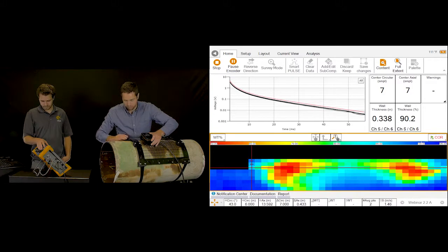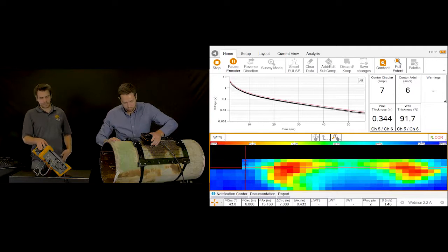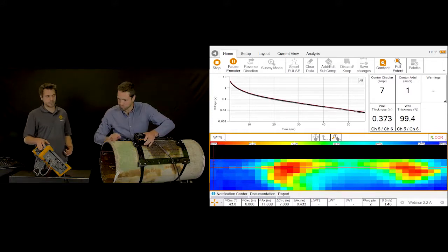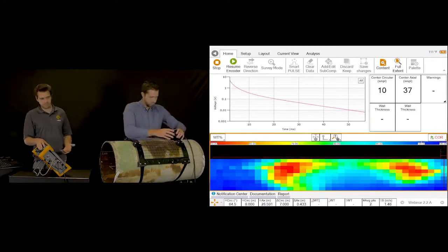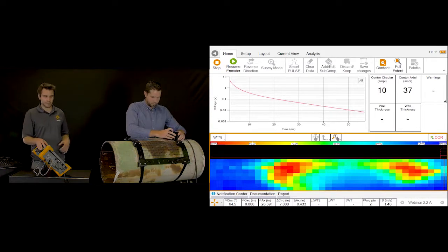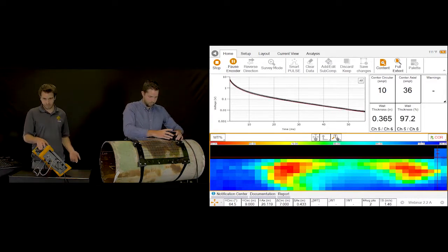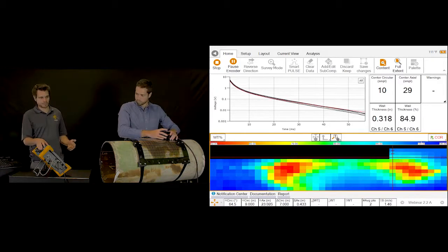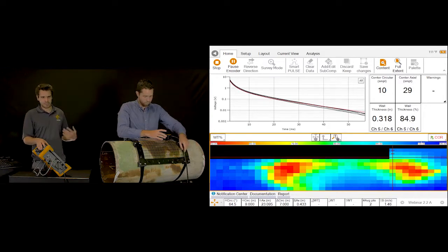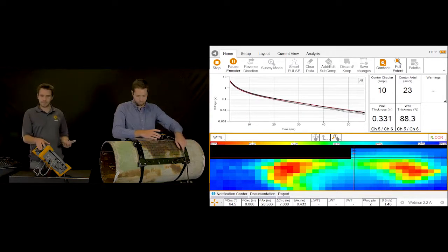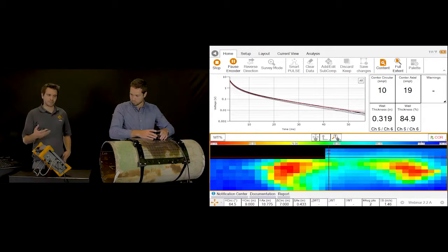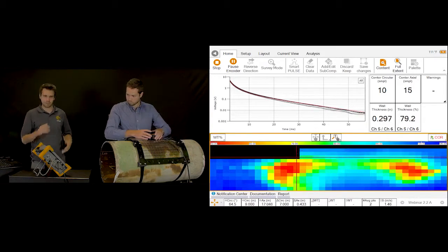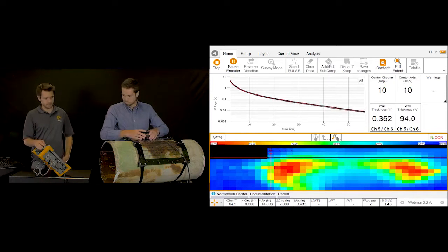Also, Gabriel can tell us about the mat. We put it in 1-inch lift-off at the moment. Yes, so this scab tool is going to give us a constant lift-off over the corrosion material, which allows, again, for better data quality. It's adjustable in height, so you can put it at 1/2 inch or 1-inch lift-off. You can also use the probe in contact directly with the surface. But the mat is going to allow you to acquire data with a higher quality, a constant lift-off. It's also going to minimize the scab effect, which is the signal distortion you can get from the corrosion material if you're too close to that scab material.